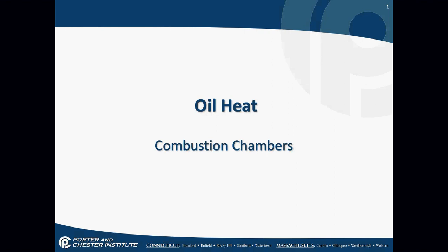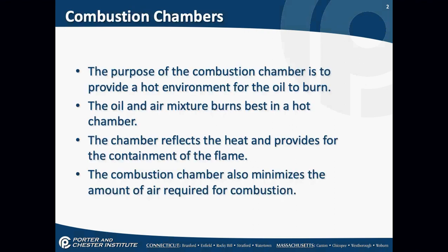Why is that a bad thing? Okay, if flame is hitting the wall of the combustion chamber, do we have complete combustion going on? No. Okay, it's all about complete versus incomplete combustion. If I have a flame hitting the wall of the chamber, it means I have oil hitting the wall of the chamber, and it's just going to be incomplete combustion, because incomplete combustion is basically unburnt fuel. Okay, we don't want that to happen.